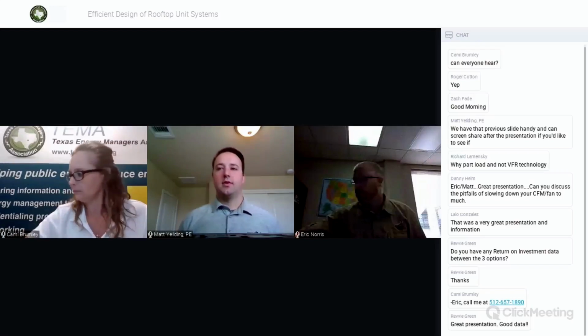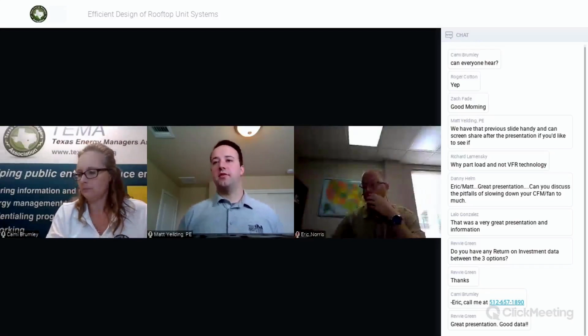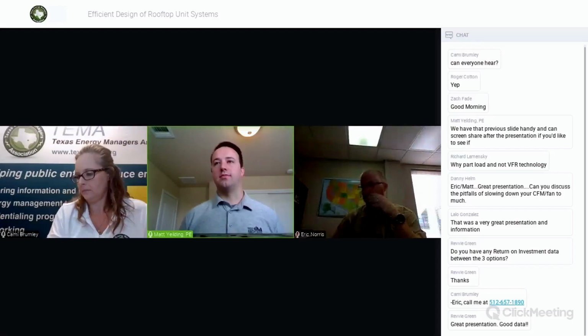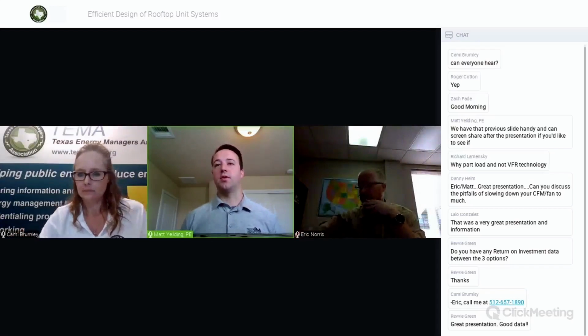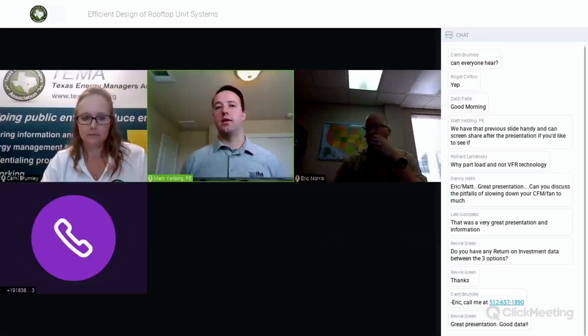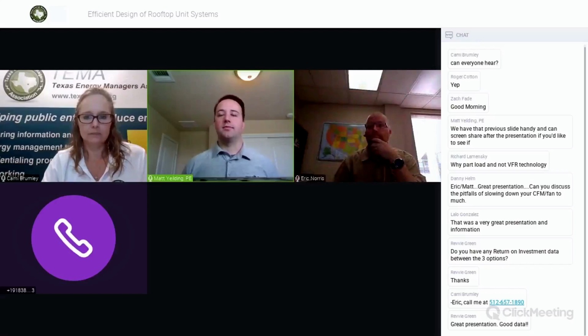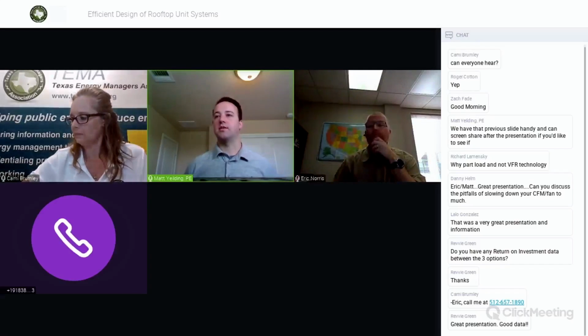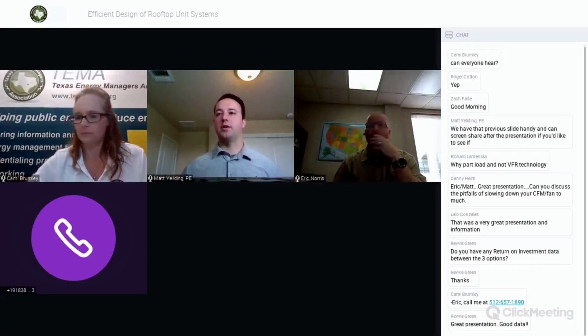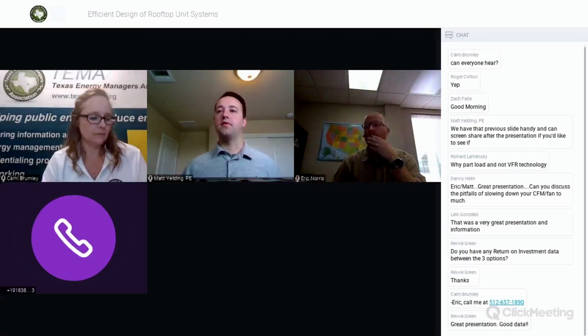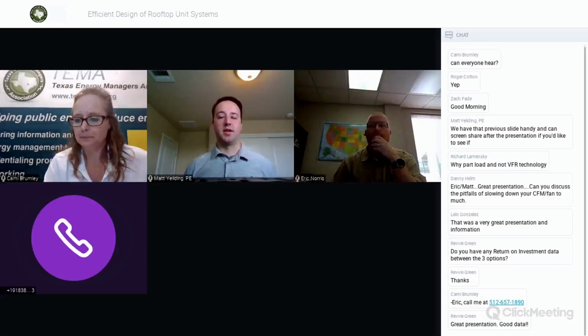Yeah, sure, Danny. There's certainly pitfalls both from a system perspective and from an equipment perspective, but the majority of those safeties are really built into the control, whether it's a manufacturer's control or a controls contractor taking control of the equipment. But certainly you've got the potential to freeze coils or those kind of things. But in a true single zone VAV system, that's not an issue, because on the refrigerant side, you're modulating both your refrigerant flow and your refrigerant temperature with head pressure control. But you also have freeze protection on the equipment.